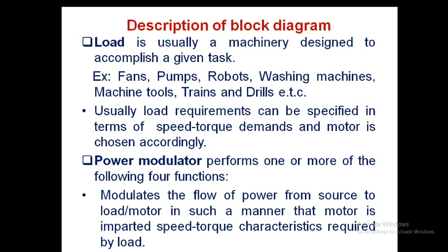To complete the task, the load is designed, and usually load requirements can be specified in terms of speed-torque demands, and the motor is chosen accordingly. A series motor or shunt motor or induction motor or synchronous motor is chosen based on the load requirement.